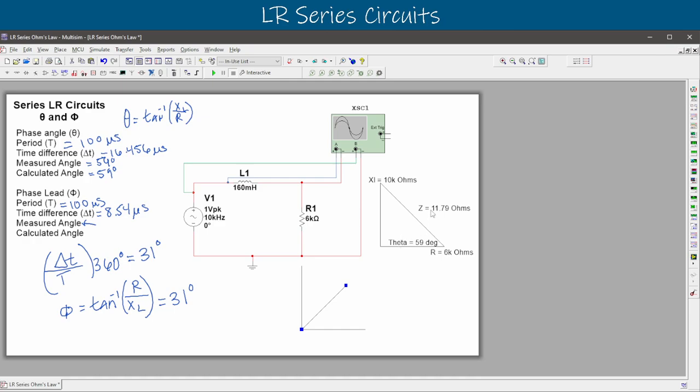Right, so let's grab a couple of these. We'll copy one of these and we'll paste it so that we can have something to paste a text box with. That gets us our text box out. Make sure your circuit's off if you're trying to paste or copy things in your zones. So this one's going to be our voltage, V in, our V out voltage there. Our voltage across our inductor, so let's copy and paste this one, is going to be up here, VL. Right, we'll copy and paste that one down here again, and this is going to be our VR, which means that this one up here in the middle is going to be our VZ, right? It's going to be the Z magnitude voltage, the voltage across both.